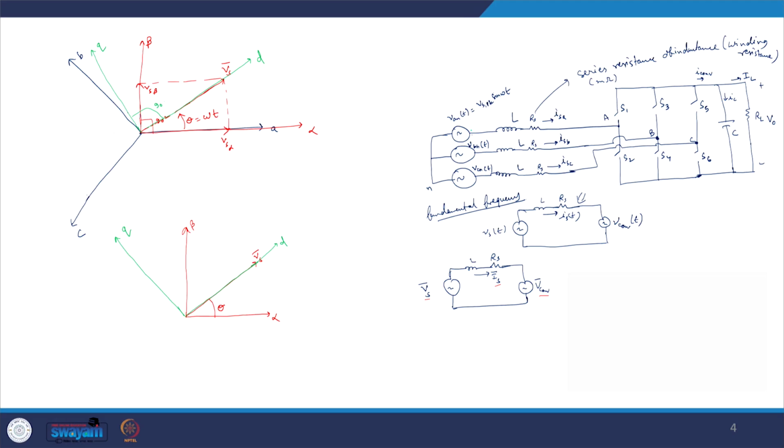It is only the Vs space vector which remains mostly constant and fixed over the operation of the converter, since they are the supply voltages, and we assume the supply voltages will have balanced operation, and the RMS and peak values will be constant over the line cycle. So, it is one of the things which we can take as the reference. It has minimal deviations. That is why we aligned our d axis along the Vs space vector, and then defined our q axis perpendicular to that.